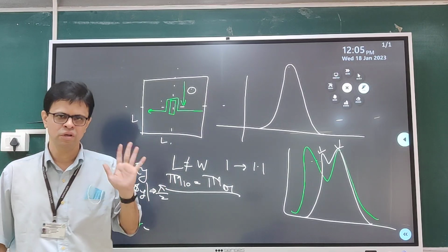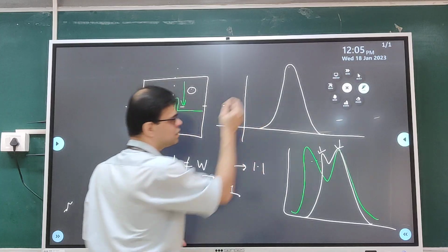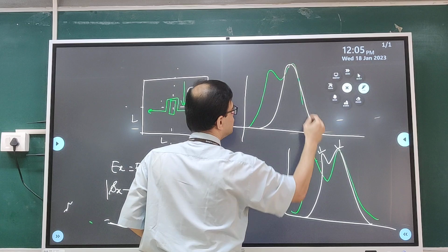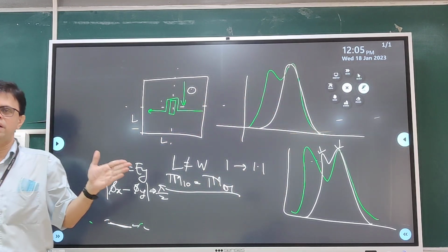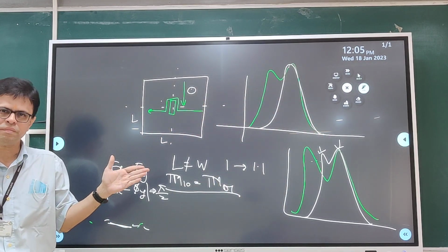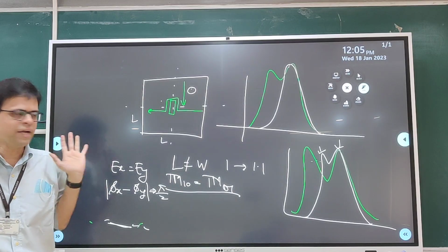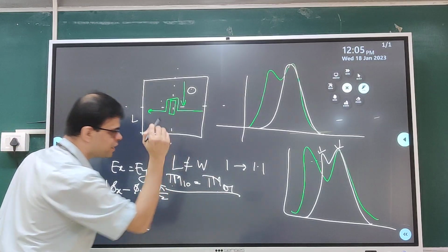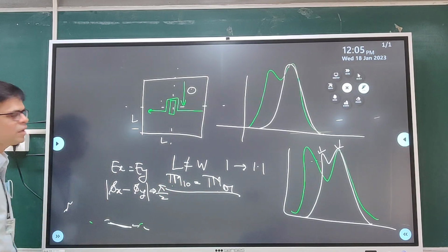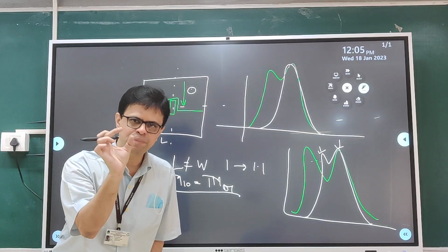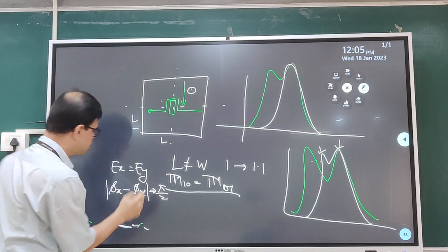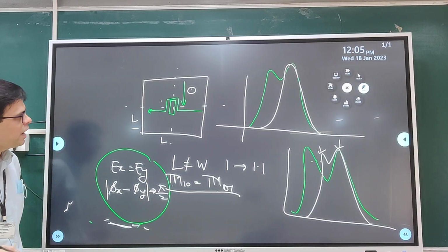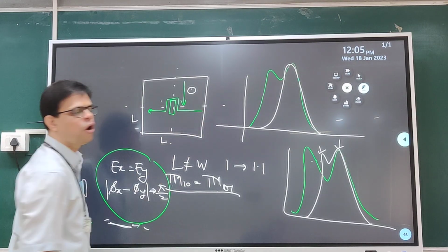Why? Frequency has reduced. Here in a single patch, rather a nearly square patch, what you will observe, two modes are starting. Observe. Two modes are present. Right? So here with this, I am ensuring two separate resonant modes. With this slot, I am ensuring a proper spacing between the resonant modes, which will ensure these conditions being satisfied, and then it will lead to the optimum CP response.